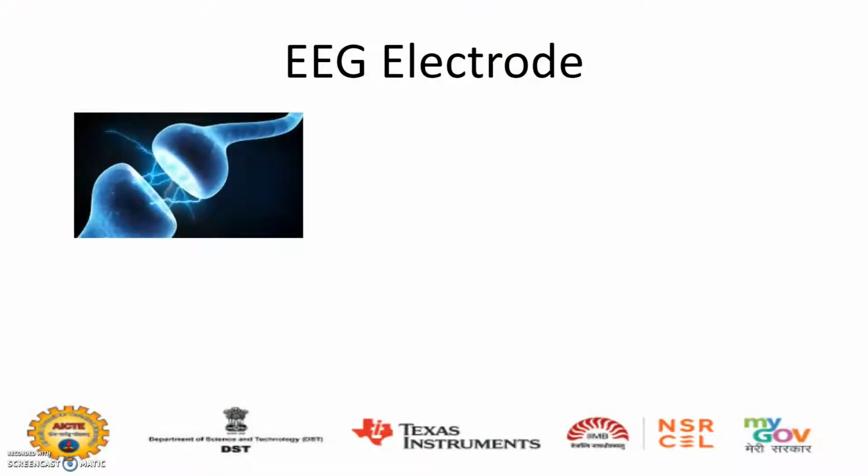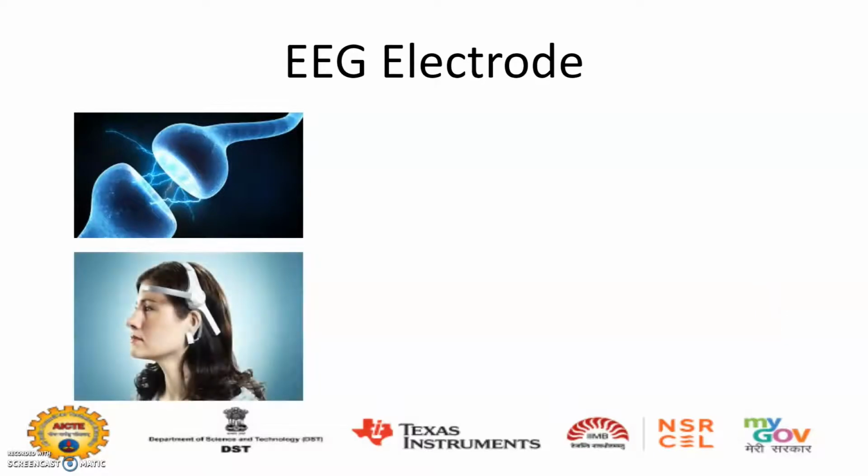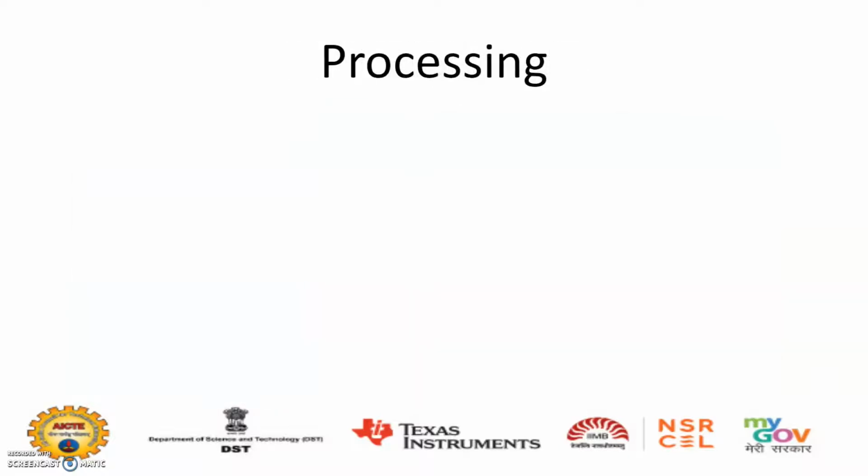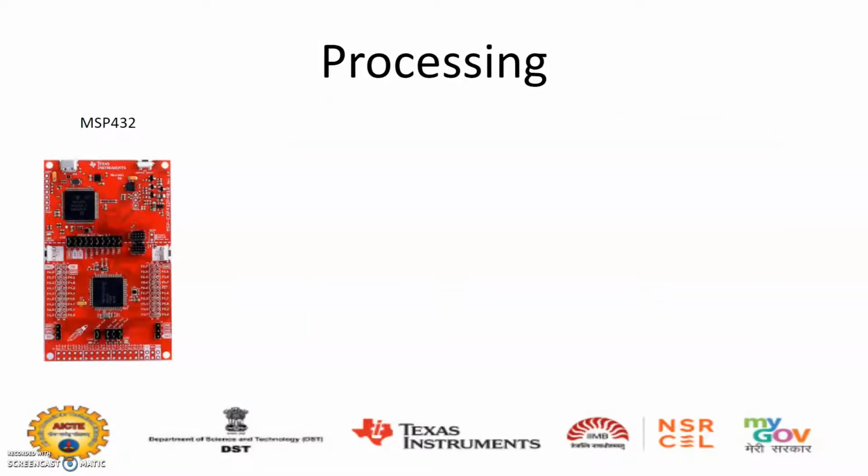Now let's talk about taking inputs from the brain. The firing of the neurons creates electrical impulses between the neurons in the synaptic gaps. These signals are captured using the principle of capacitive coupling, where an electrode with a conductive plate is used to sense the impulse. This impulse is a very small signal, hence an instrumentation amplifier and a differential amplifier are connected to amplify the magnitude of the signal. A combination of these electrodes connected in a daisy chain connection will give us the signal to control the system. This signal is transmitted to the microcontroller.